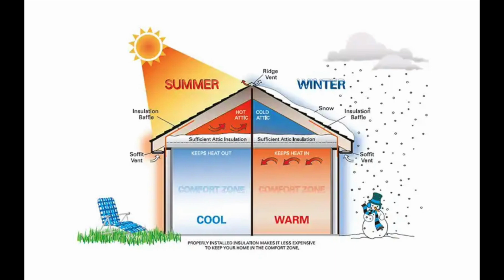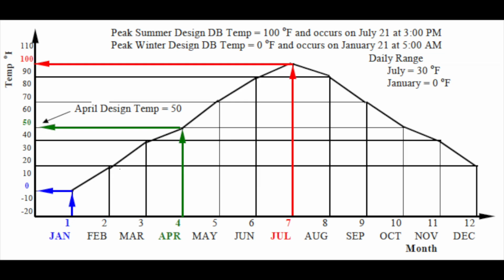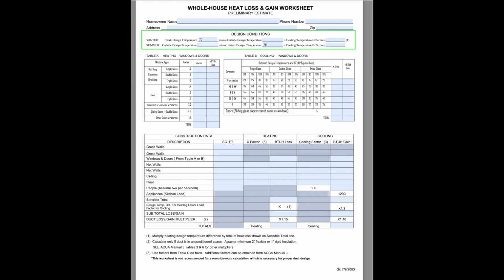That would make the system oversized and inefficient. Instead, engineers use climate data collected by ASHRAE and weather stations, and they find out what is the average temperature that they've found to be hot or the average temperature that they found to be cold. And so these outside design conditions give us a realistic challenge for systems without going overboard.